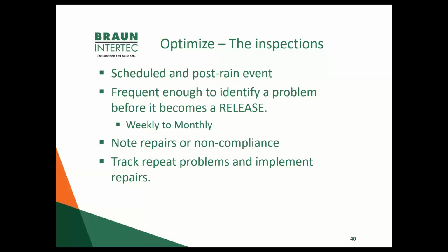Yeah, and I've had sites too, Josh, and I'm thinking in particular of production facilities, in some areas where we use judgment on whether your containment is sufficiently impervious to be protective and prevent a release. If the containment is not really impervious, that may be a situation where we recommend a more frequent inspection regime, because you need to have boots on the ground often enough, looking at things to make sure that you don't get a loss of fuel outside of your containment.